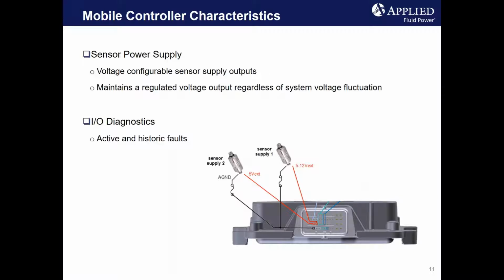Where I/O diagnostics come in handy is when the control system has an HMI or a display screen, where you can have a diagnostic screen within that display for troubleshooting your I/O. It can simplify your field service time.